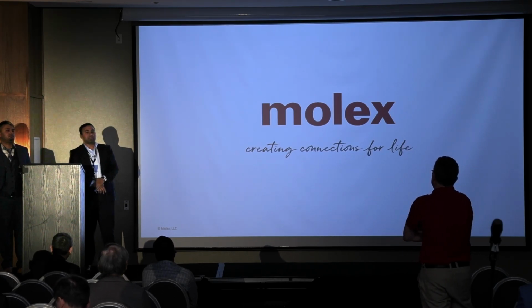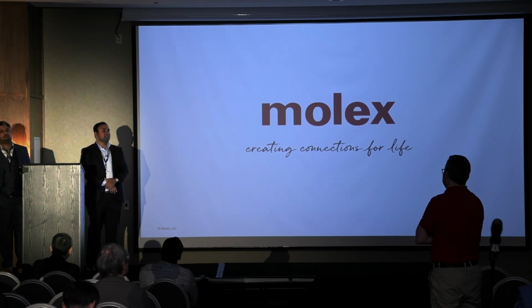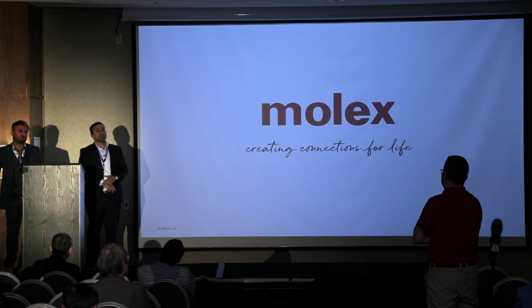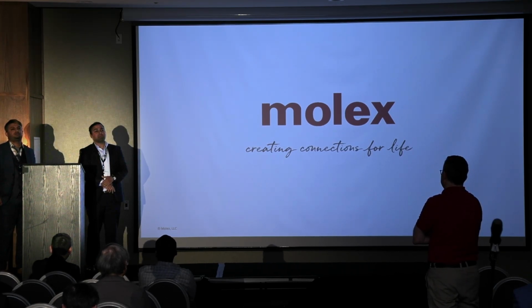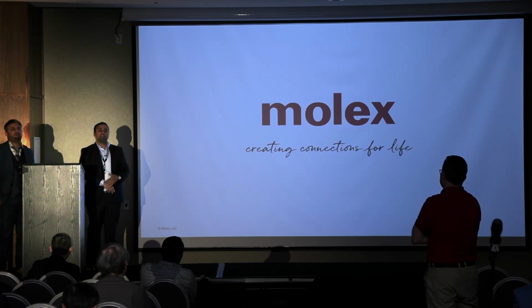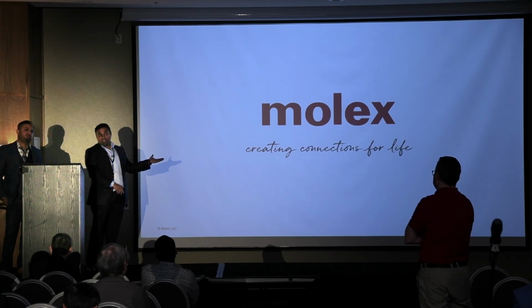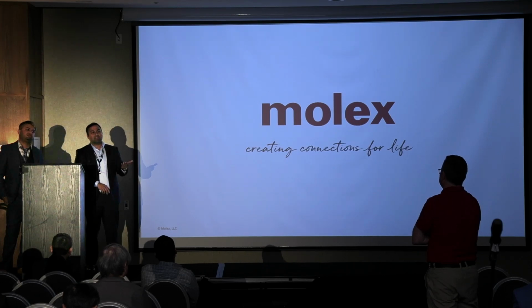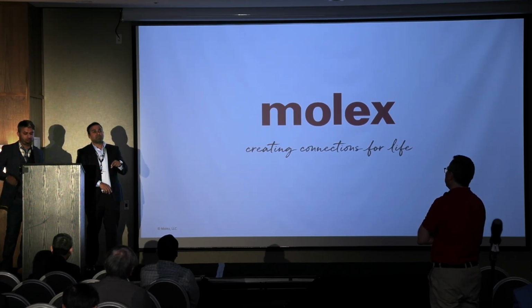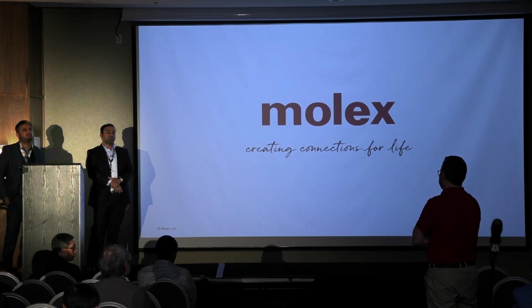Yes, I could answer from my side, and then I will let Safal add too. Yes, it can happen because, like I said, it's all about the layout. Whether it's STP or another system or coax, it's all about how we are laying out the system and how we are balancing every component around it. STP is the same thing with the cable. If the cable is improperly constructed, like the example we have seen, it can lead to mode conversion, or from the PCB side or the connector side, because regardless of which is being used, proper symmetry and construction are very important for the overall impact to consider.